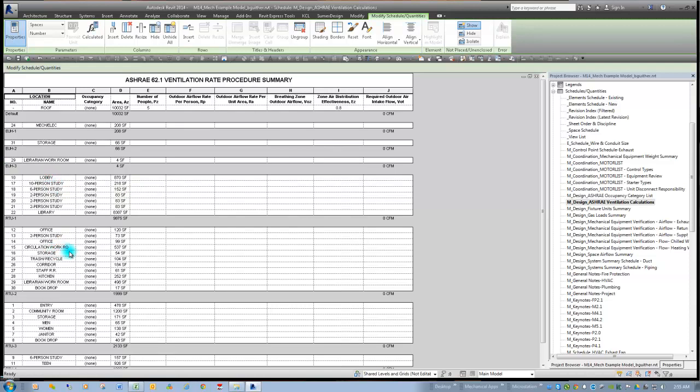Now I'm going to go through and choose the ASHRAE spaces that match closest. You can hit this pull down, and then in this window, you can hit the first letter to get you close to your space type. We'll make this one a conference meeting room, and we'll do that for these ones as well.